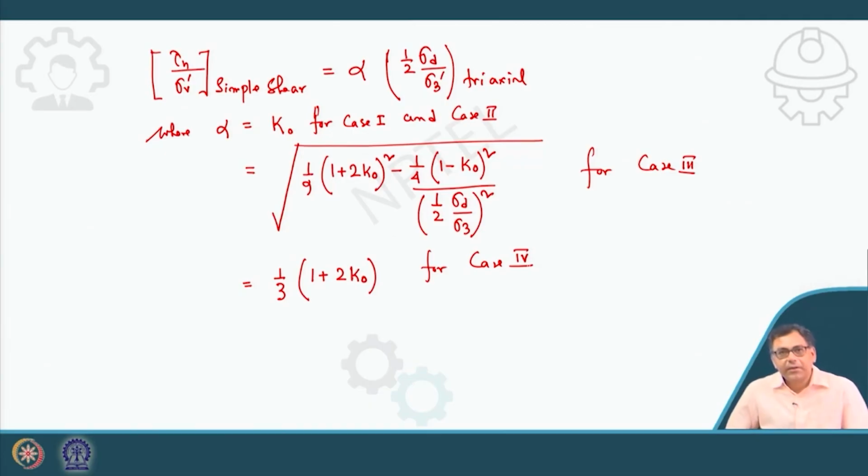Okay. So now I can correlate the CSR of the cyclic simple shear test with the CSR of the cyclic triaxial test by using these equations.